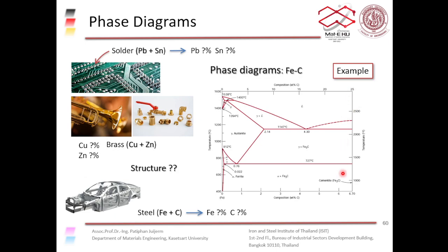And because this is an intermetallic compound, Fe3C, you have a fixed stoichiometric ratio of the two types of atoms. Because of that, you don't get a wide phase field, or you don't get a solubility limit. You get just one line coming up from this point here, right?